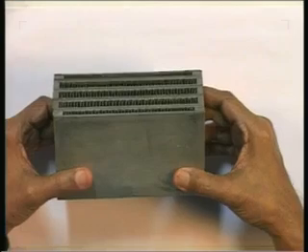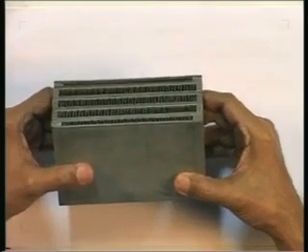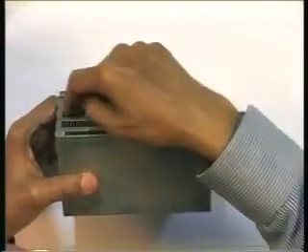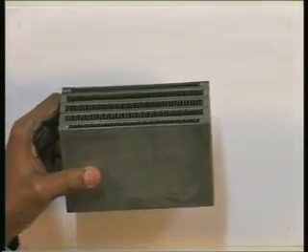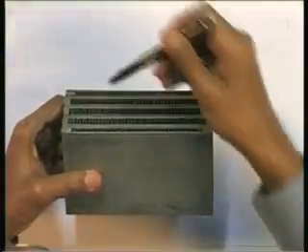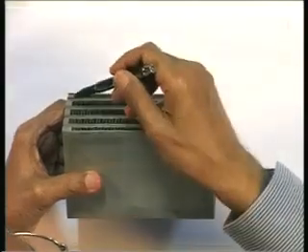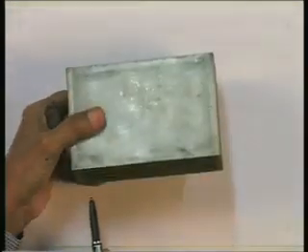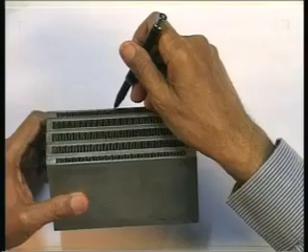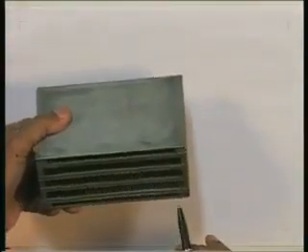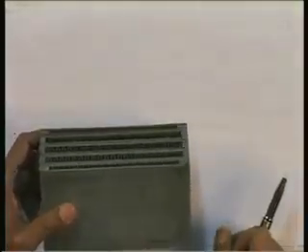Now, there is something more which I want to also say. This is a cross flow arrangement, but mind you, in addition, what is to be noted is we have got fins here. Now, when you have fins in this heat exchanger on both sides, both on the hot side and the cold side, a fluid particle which enters here, say in this passage, will go through the heat exchanger and come out at this end here. It has no choice. A fluid particle which enters here has to come out at this point. A fluid particle which goes in here has to come out at this point. You understand? Because the fins make passages right through along the length of the heat exchanger.